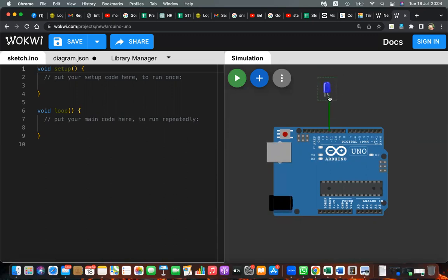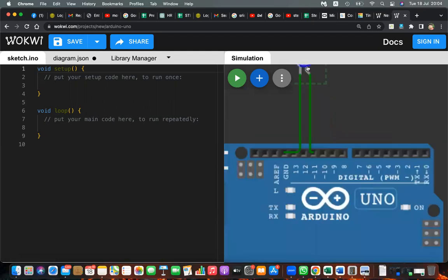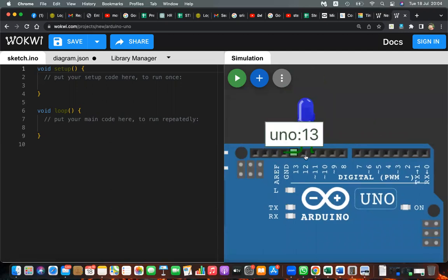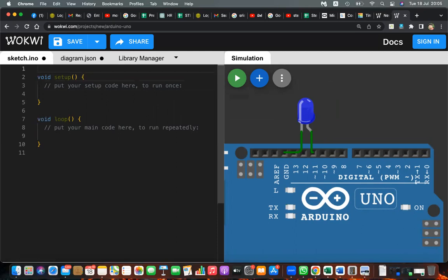And the GND pin, the ground pin, I'm connecting via this one, GND. See the connection. GND and 11. So I can define this pin as the LED pin. In the beginning of this code, int LED is connected to pin 11. So I can say